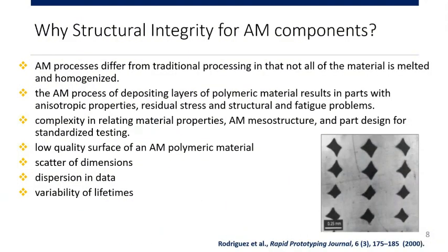Why apply structural integrity to these components? First of all, as I mentioned already, these techniques differ from the traditional processing techniques in that not all the material is melted and homogenized. The process of depositing layer by layer of polymeric materials results in anisotropic properties, sometimes introduces residual stresses, and there can be issues related to structural and fatigue problems.